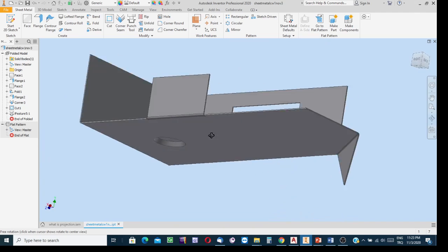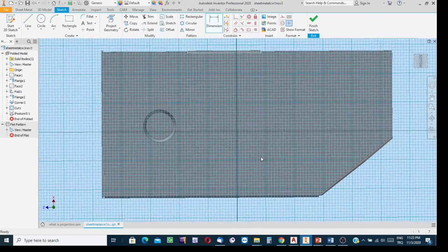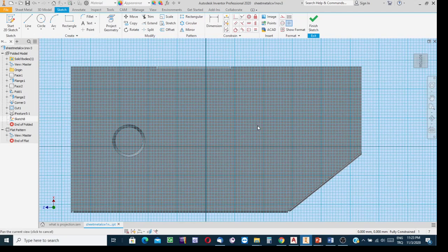Well, in this case, mark the center of the emboss at this side. Then at this side, I'm going to have the emboss, but the other side, empty space, blind empty space. Take a sketch right over the surface and then say new sketch. And then select point marking process, of course. Mark the point. It is in the mind to consider the center of the flat surface of the emboss.